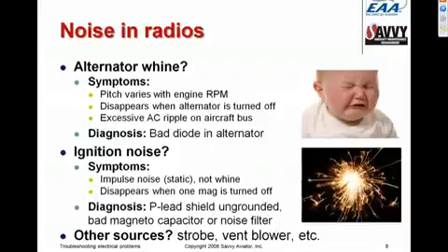The other common source of noise in the radios, and in fact I just had a problem with this on my own airplane that I had to fix a couple weeks ago, is ignition noise. Ignition noise sounds totally different than alternator whine. It is not a tone. It is, for lack of a better word, it sounds like static.